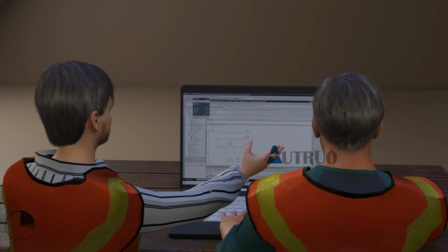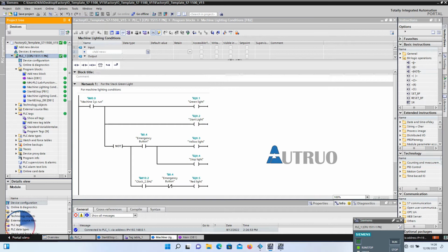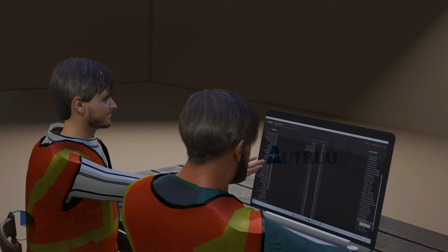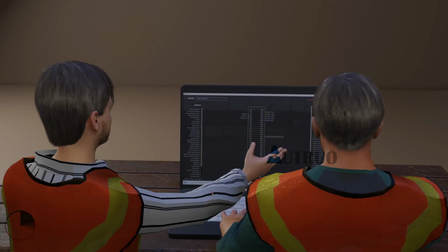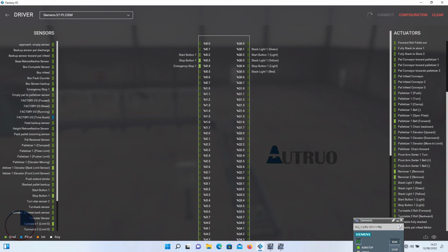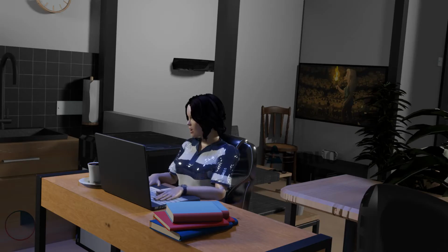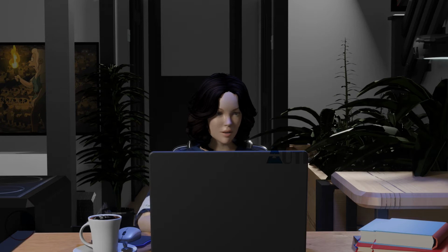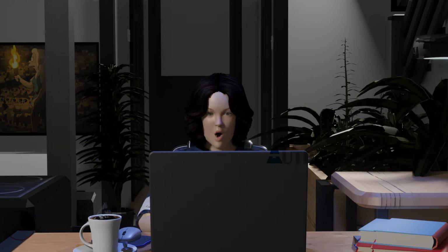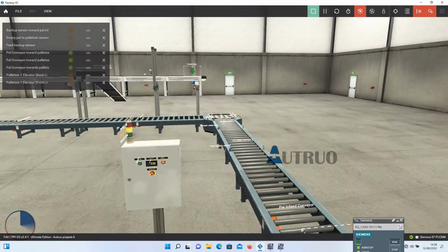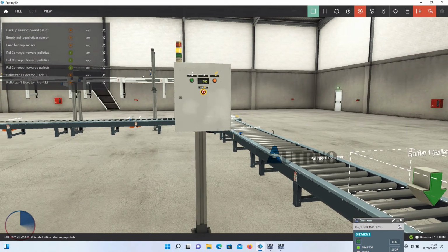We will now download the written program to our PLC sim. Also, we will need to drag the I/O to the respective bit addresses in the simulating software. In our case here, we are using Factory I/O. Perfect. Most especially the blinking output coils, these will easily catch the attention of the operator and those around the equipment at that point in time. Again, these lights are not mere bystanders when it comes to machine design.